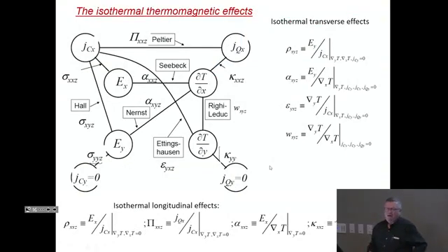Okay, here comes a very important part of the class because most people are confused about this. Just like in resistivity, there's a difference if you measure the electrical resistivity while ensuring that the sample remains isothermal, or if you measure the electrical resistivity while ensuring that the sample has no heat escaping it. There's no heat escaping it, you have an adiabatic measurement.